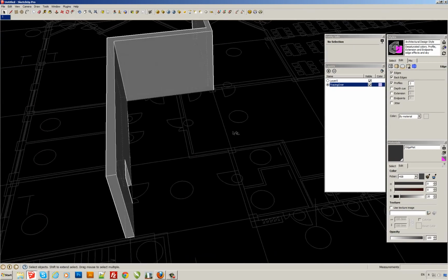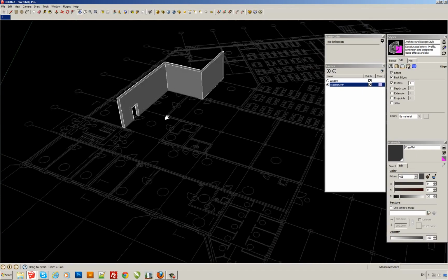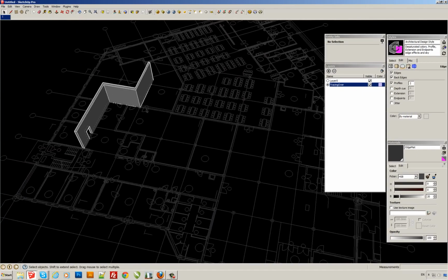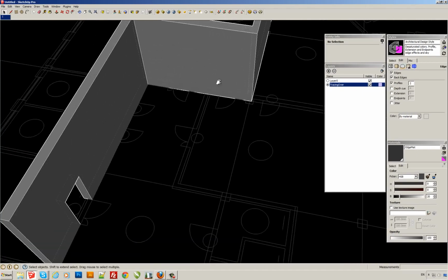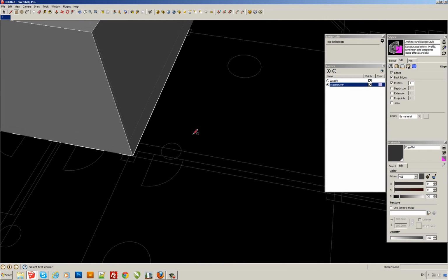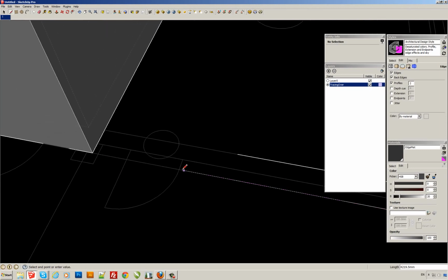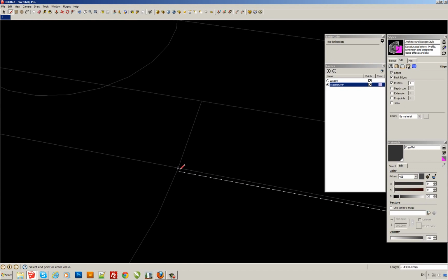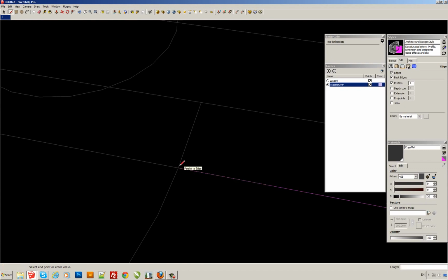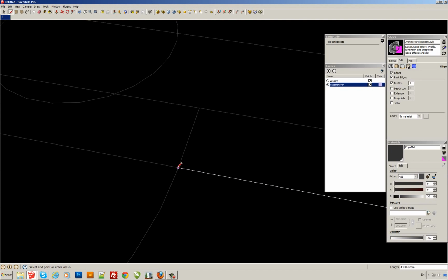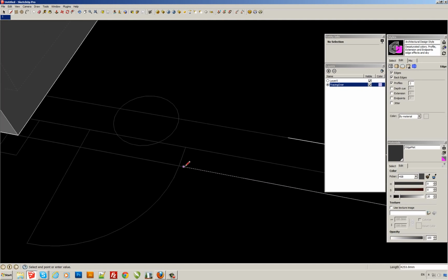Of course, there are a lot of additional tricks you should know to avoid unparalleled wall creating, like something like this. If you are snapping to some points, you can snap to many intersections, so avoid some crossing points.